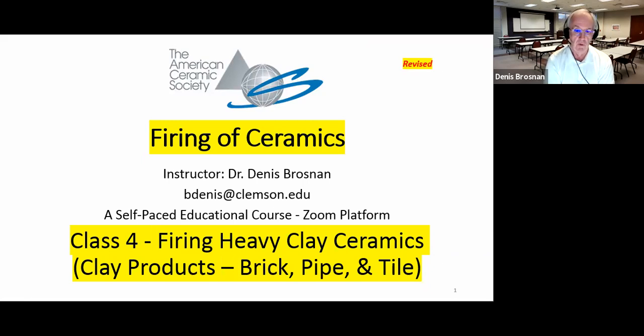Now, we're going to have 3 classes, including today's, which is going to look at specific types of ceramics to be fired. The whole purpose of this is to show you that there's a correlation between things happening within the ceramic and things that you must do in firing the ceramic, particularly with respect to adjusting the firing schedule, meaning the heating rate or cooling rate.